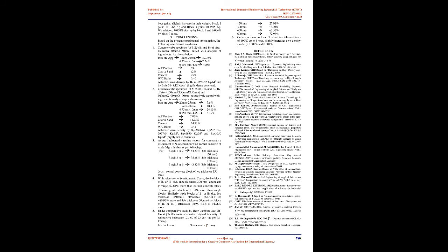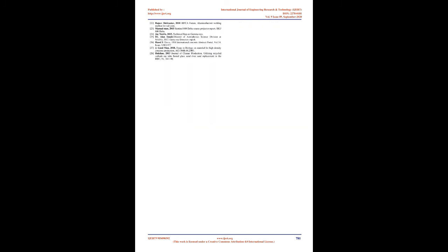Initially the free water content is about 3% by weight. The water may be lost at ambient temperature by evaporation. To minimize evaporative loss, the design criteria limit of ambient temperature is 149 degrees for photon shield and 71 degrees Celsius for neutron shield. Maximum internal temperature for photon shield is 171 degrees Celsius and 88 degrees Celsius for neutron shield.